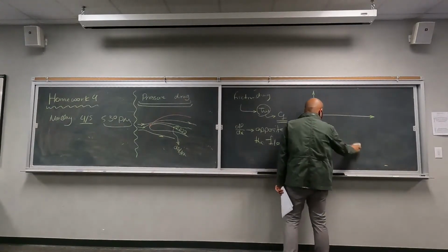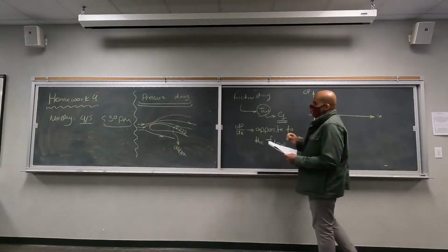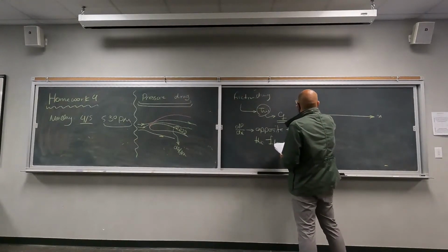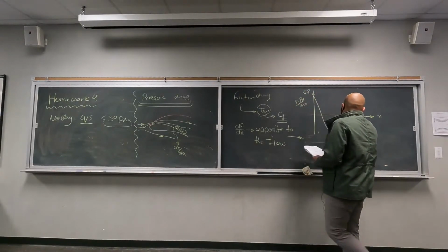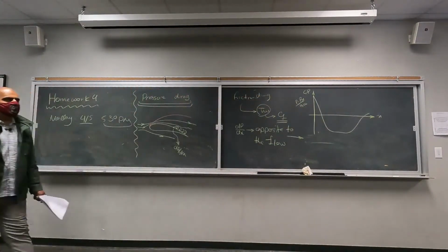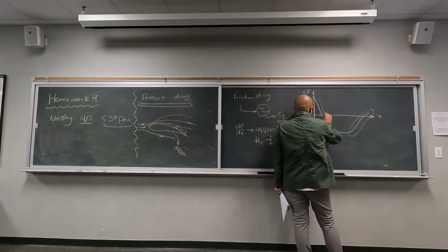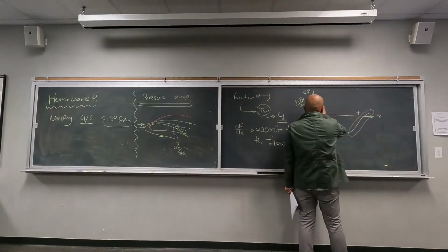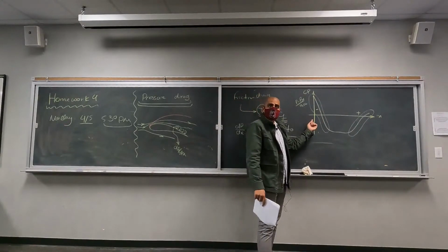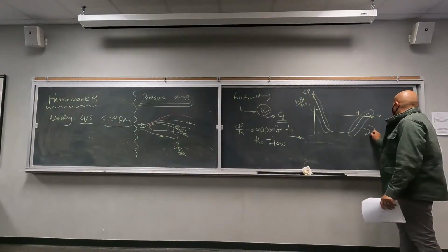Let's take a look at the pressure gradient with respect to x. This is the pressure coefficient on top of the airfoil. You start with a very high value, P minus P infinity divided by Q infinity. That's your pressure coefficient. Then it goes to a minimum location, and then it comes back up to a positive value. As you can see here, the slope is negative, and then the slope here is positive. This negative slope is very consistent with the flow, because flow moves from high pressure to low pressure. But on the other side, we are going to have flow separation, so flow is going to move back.